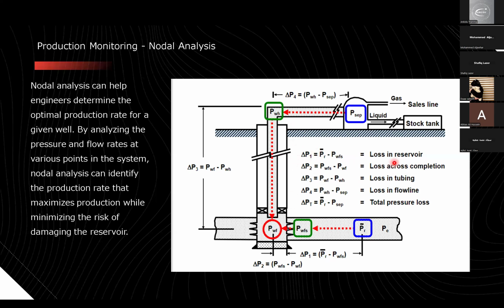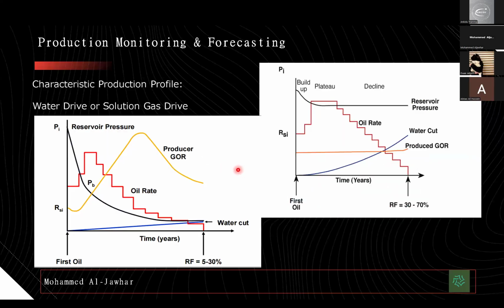Is it related to reservoir pressure, or is there something inside your well bore in terms of skin, etc.? How can you remove this skin, for instance, and keep your well flowing? So this is one type of data you have to think about: where you have a loss, is it in the flow line or tubing, or do you have total loss in your production system.